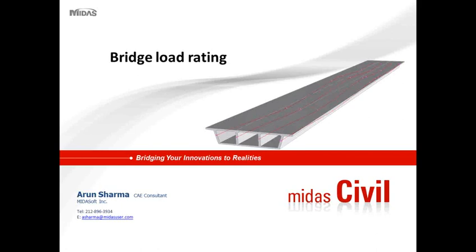So we are getting some questions here. What is number of tendon meaning? So basically, certain tendons are clubbed together and represented as one tendon. So you can define just one tendon profile, and in fact, as you can see in this display, there's just one tendon profile, and we entered number of tendons as 6.